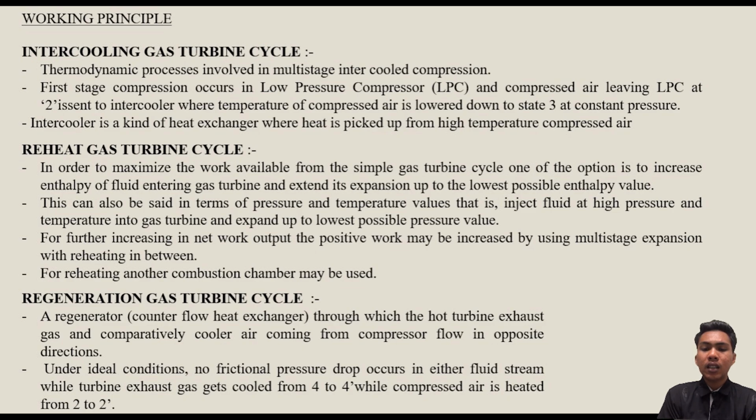Lastly is the working principle of the regeneration gas turbine cycle. A regenerator is a counter flow heat exchanger through which the hot turbine exhaust gas and the comparatively cooler air coming from the compressor flow in opposite directions.